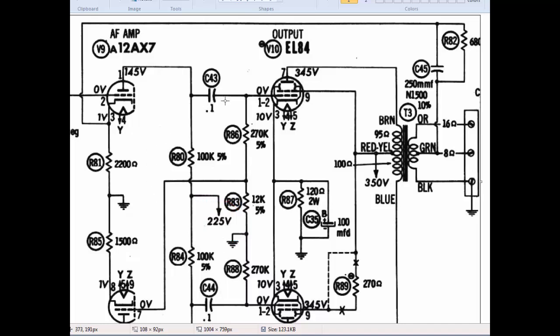And let's take a look at a few voltages that are inside of this tube amp. So if you measured relative to ground, this point right here, which happens to be the plate, this top little symbol, you'll start to learn some of this. This little symbol right here is the plate of this EL84 output tube. It measures 345 volts relative to ground. Hey, that's a lot of voltage. So you'll get used to seeing, when you look at the plates of tubes, there's an awful lot of voltage sitting on those, and that's what those plates need to operate properly. You'll learn more about that when we get into how tubes work.